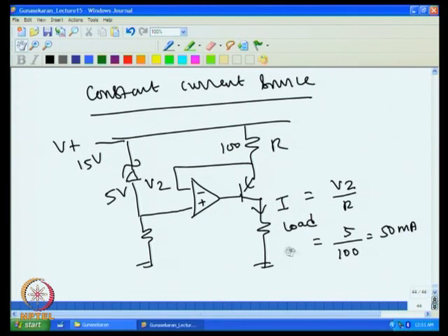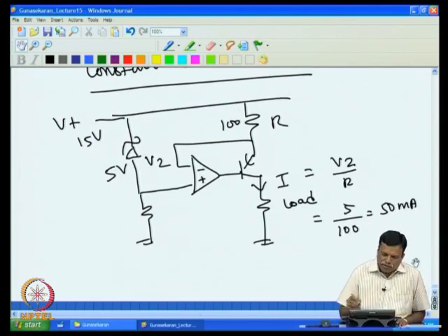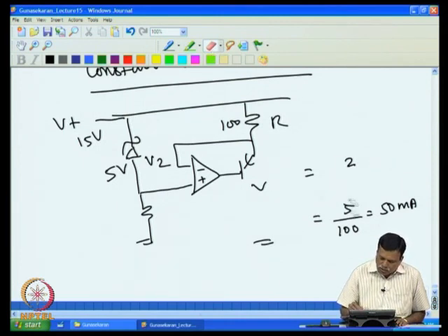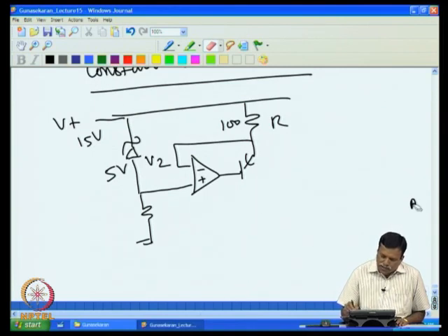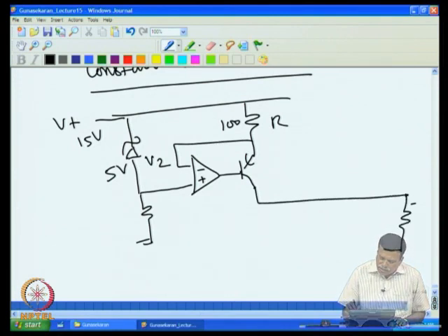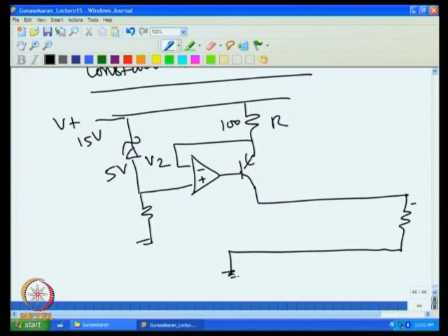Now if I use this current source, I transmit this for a long distance, and I want to convert this current into signal and power, because the same current source should power the remote device, and the current information also has to be taken and used to control the valve, etc. So normally what is done is, I remove this load, transmit this for a long distance, have a load here, and then bring it back to the ground. Now this current will vary if I vary this resistance.